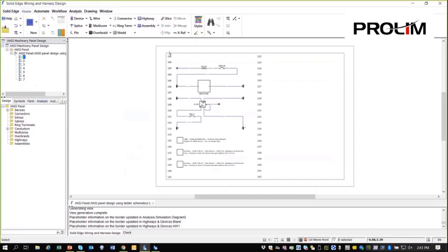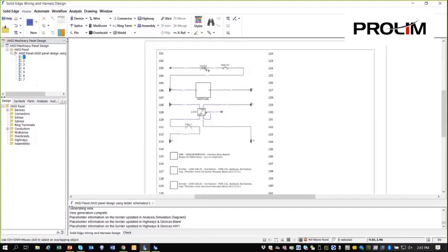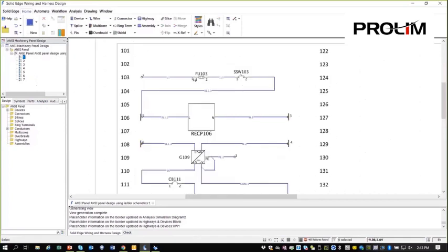Okay, I'm going to leave zoomed out here for this view. I'm going to zoom in a little bit, but I wanted to show you the numbering scheme, the 101 down to 121, 122 to 142. So those of you doing ladder diagrams, you're going to want to be able to set up these title sheets to do this. And what we're looking at is when you place a component in the proper position, the name is inherited by the position.